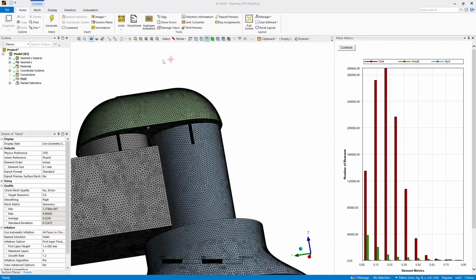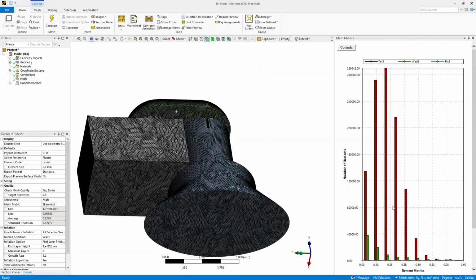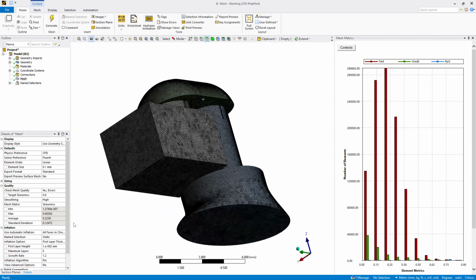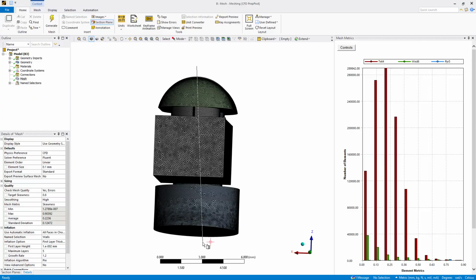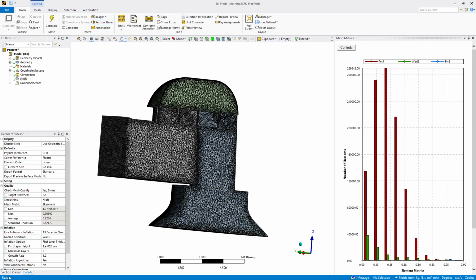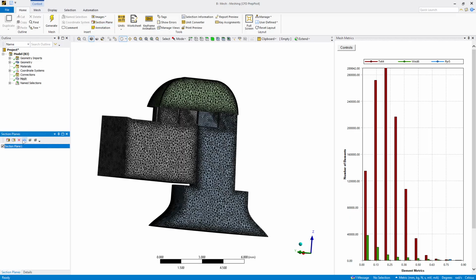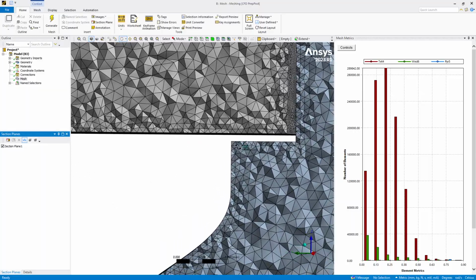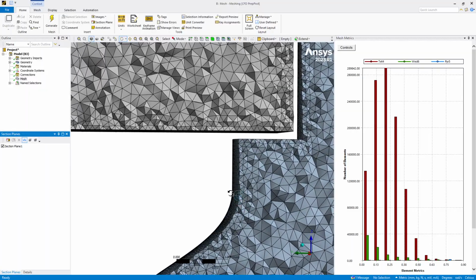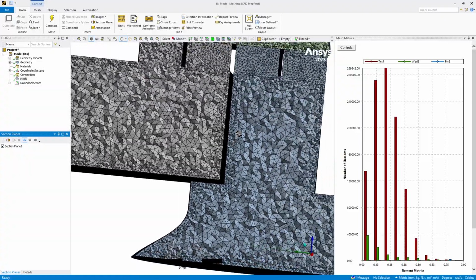Okay, we have a mesh and we have some element quality showing. The skewness did come in below 0.9, which is good, and the inflation layers, if we draw a section plane, can be seen, especially if you turn on this, and here we see the few inflation layers, maybe a smaller value.